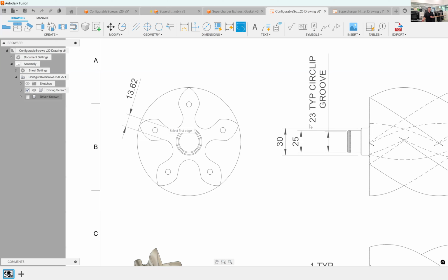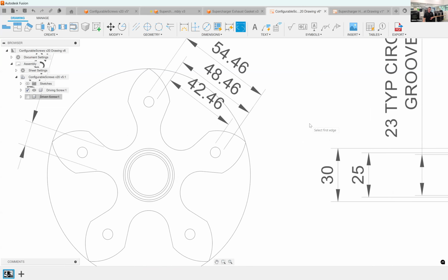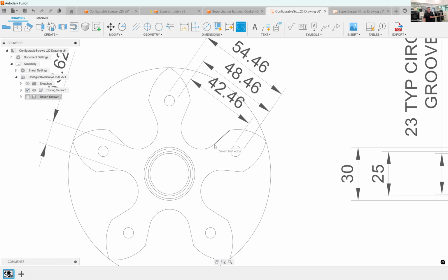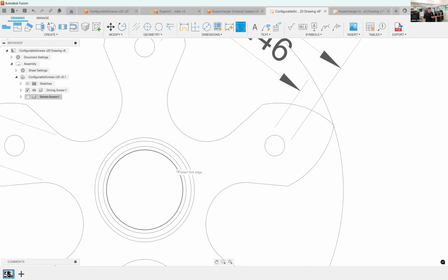And I know that those numbers are perfect because these holes are 8 millimeters and these are all 4 millimeters apart. So I know, as a quick sanity check, that it has gone for my minimum and maximums there. This tool can also do dimensioning between concentric circles. So if I wanted to know the distance between my inside shaft, well, that would be the chamfered edge. So I'll do the middle one and the shaft edge here. You can see I can choose that 1.5 mil.